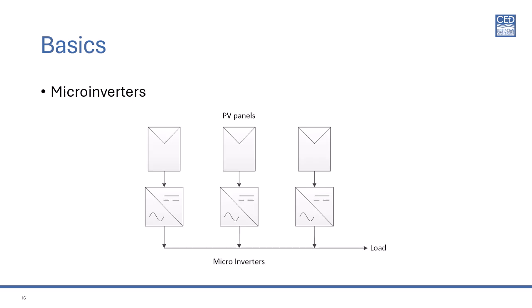Another type of inverter is the microinverter. These are small inverters, about the size of a paperback book, and typically will have one on every panel, or maybe one over every 4 panels. Microinverters are distributed across the entire array, rather than being in a single remote location.